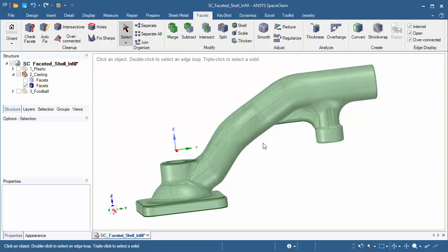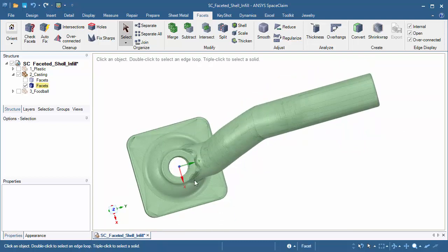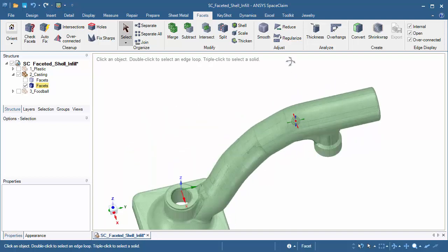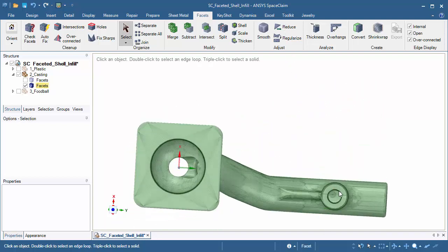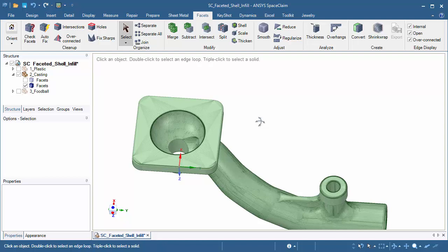So if I scale it, the distance between this axis and this axis changes. When you offset, there's no reference that it's scaling away from. Everything goes in a normal direction. So here they would collapse in on this axis. These would collapse in. So for a lot of very important dimensions, shelling, offsetting is needed over scaling.